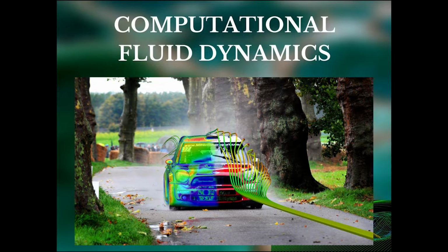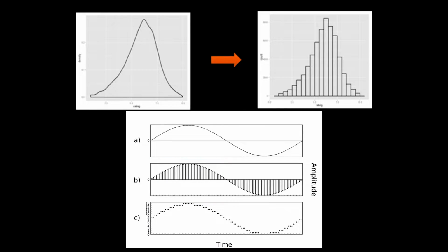Now let's see how we use CFD in these scenarios. It involves three steps. First is the discretization, second comes solving, and then post-processing. Discretization is the most important step as it involves breaking down the body into very small pieces. As we have broken down our problem into small pieces, we can make linear equations for each and solve them accordingly. All these methods are to approximate the differential equations.